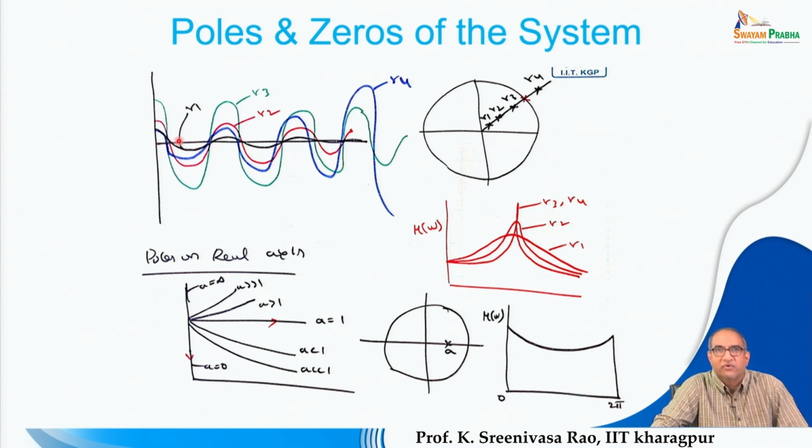That is the reason, because if you try to analyze the frequency offered by the complex conjugates of R1, here I have not shown the other part of it, a mirror image of this. R1 has its complex conjugate, similarly R2 also. If you look at R1, R2, R3, R4, all of them have the same frequency of oscillation, but R1, R2, R3 are damped sinusoidals.